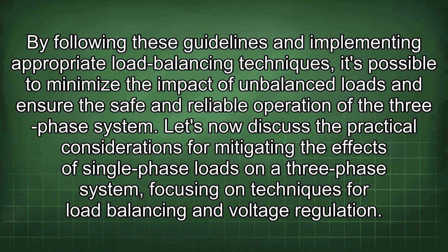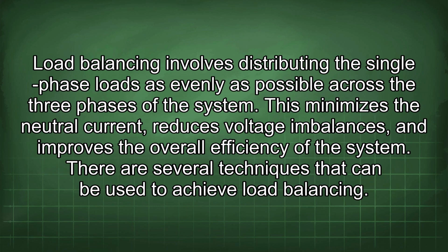Let's now discuss the practical considerations for mitigating the effects of single-phase loads on a three-phase system, focusing on techniques for load balancing and voltage regulation. Load balancing involves distributing the single-phase loads as evenly as possible across the three phases of the system. This minimizes the neutral current, reduces voltage imbalances, and improves the overall efficiency of the system.